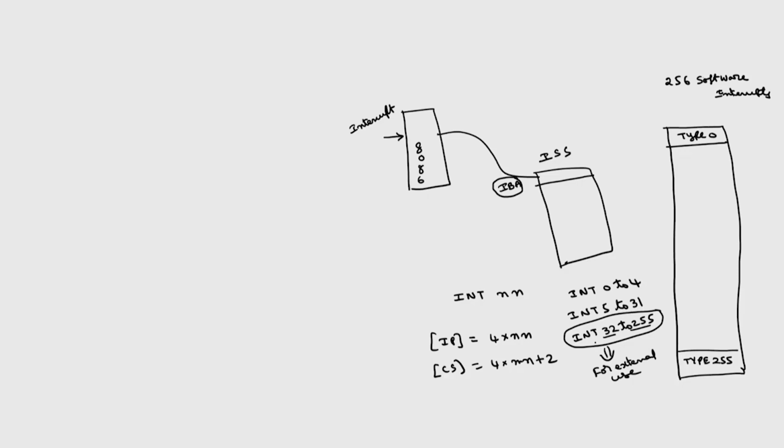For example, if I use INT 32 type of interrupt for IR0, say I want to operate IR0 in type 32, what are the corresponding addresses? 32 times 4 is 128 in decimal. For hexadecimal, 16 times 6 is 96, 16 times 7 is 112, 16 times 8 is 128, with 0 as the remainder; 16 zeros, 8 is the remainder, so 80H.